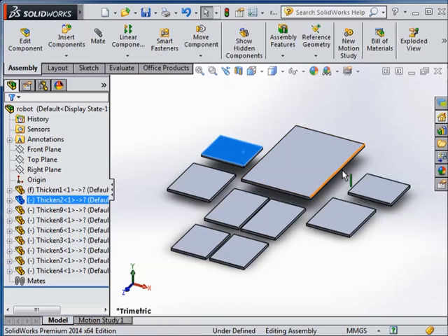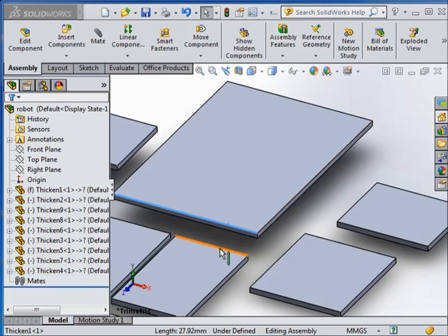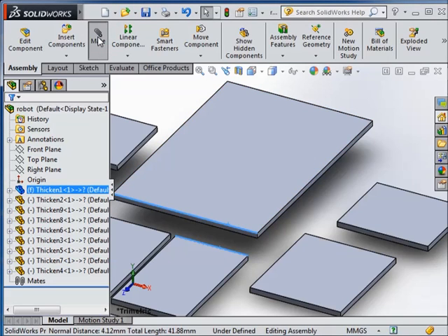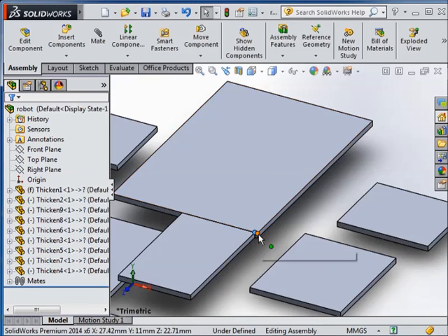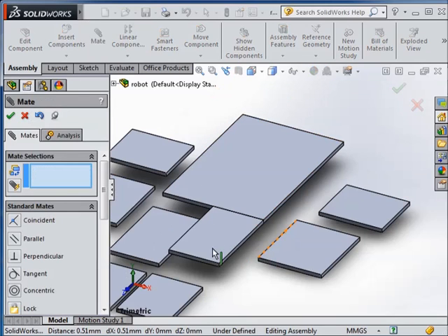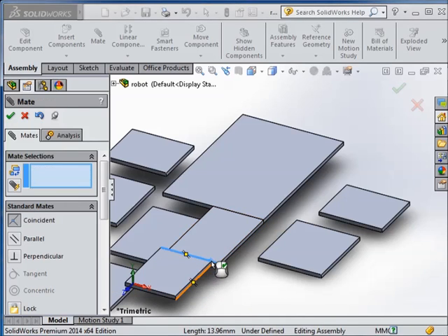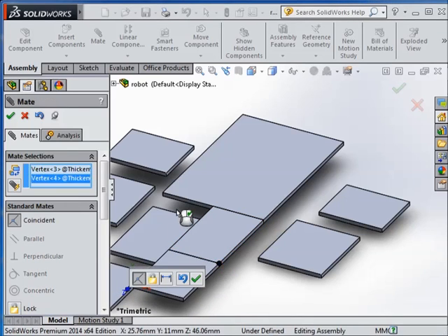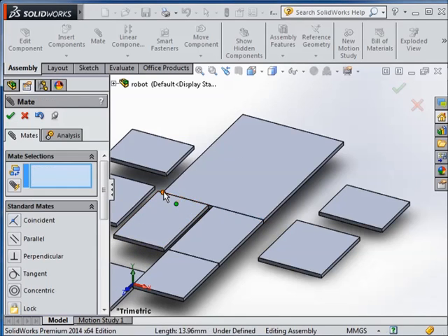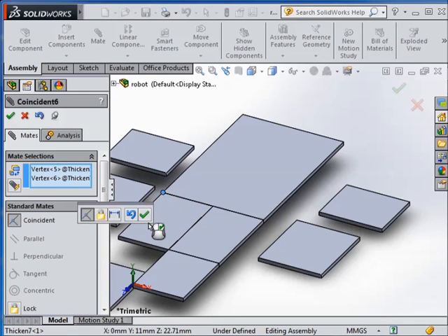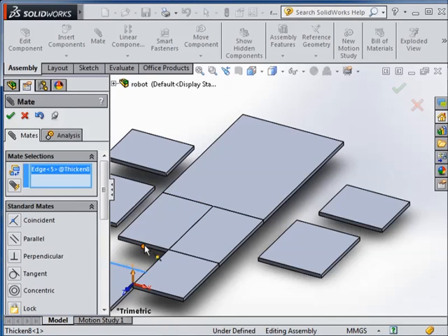When you're creating a mate, you need to define several things. In this case, I choose the top surface as the mating entity because it's frankly quite easy to do so. In general, if you wanted to create a perfect representation of a laminate device, you might pick the midpoint, or the mid-plane, between the top and bottom surface. This would be a little bit more kinematically realistic. Right now, however, I'm simply doing this for a quick demo, so I don't care as much. Also, because this is a one-layer device, it matters even less.